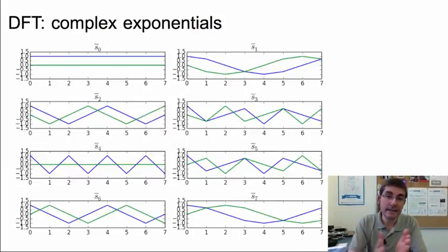If the signal has size n equal 8, we will need 8 sine waves, like these ones. So here we have the 8 complex sine waves, starting with S sub 0, with this DC component all being a constant, S sub 1, which will have this one period of a sine and of a cosine, and we will keep increasing the number of periods, but as you can see, there is some symmetry, and the frequency doesn't go up to 8 periods, but it really goes back to the 1 period.